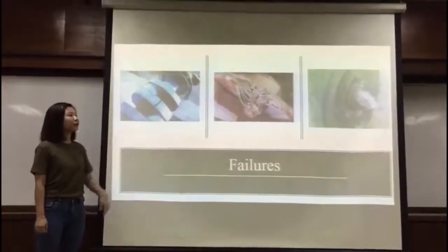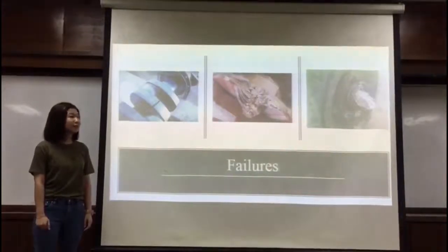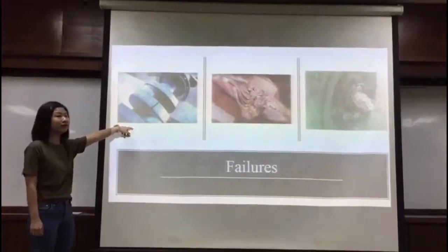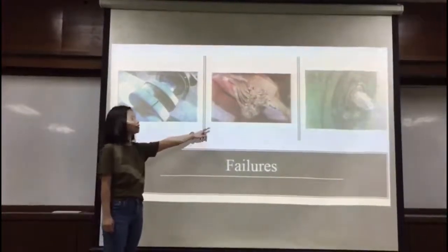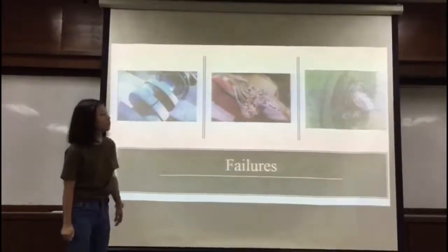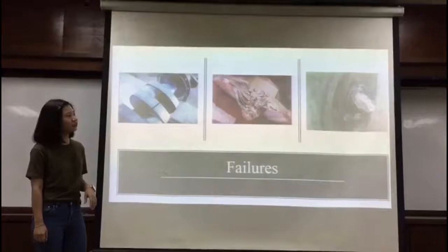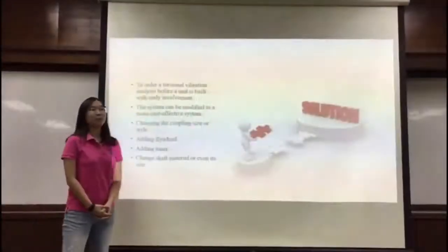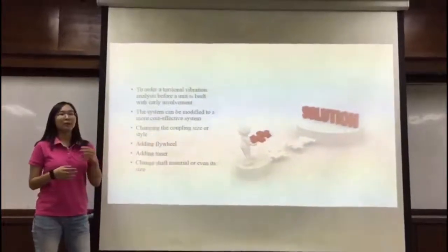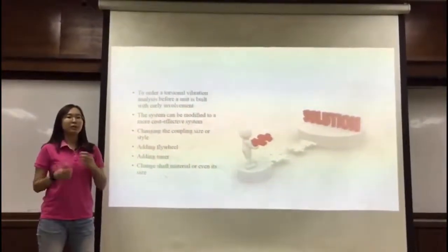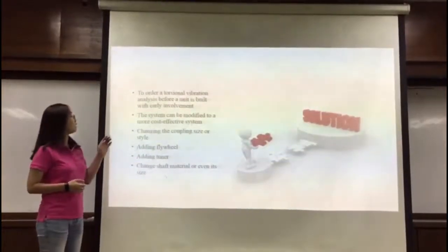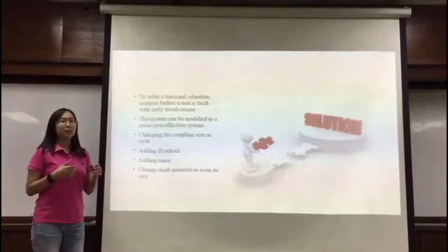These are the consequences if the system fails. First is the broken crankshaft, the second is the destroyed couplings, and the third is the broken engines. Next I will be explaining the solution, which can be set as some suggestions to improve the system. First is to order a torsional vibration analysis before the system is built.